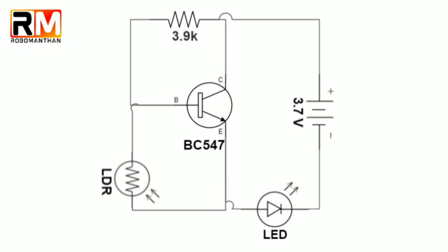In darkness, the high resistance of the LDR restricts the flow of current through the potential divider circuit. The limited current flow results in a smaller voltage drop across the resistor. The higher voltage at the base terminal of the transistor keeps it in an on state. With the transistor turned on, current is allowed to flow through the transistor to the bulb. Consequently, the bulb remains illuminated even in the absence of light.